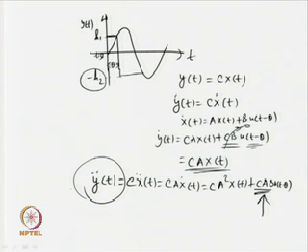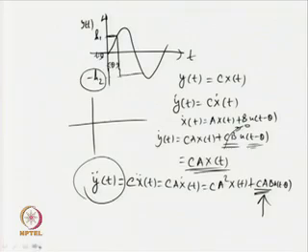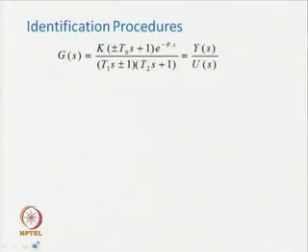So, analysis also shows that there will be abrupt changes in the second derivative of the output signal at a certain instant of time, and if that time can be tracked properly or correctly, then information about the time delay of the process can be obtained outright. And this is how one parameter of the transfer function model can be obtained from the output signal or from the derivative of the output signal conveniently.